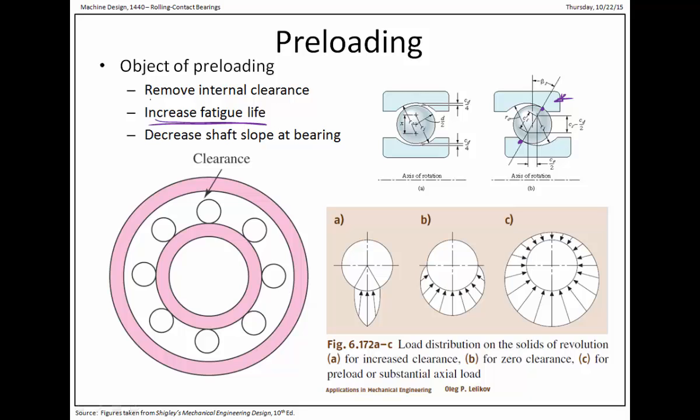One thing I think is a good way to associate this is that it removes any gaps or clearances that you might have. If you can imagine, if there was no load going on right here axially, this ball could move all over the place because of the little tiny gaps. By having a preload on there, it establishes where the points of contact are going to be. And like I said, it also generally increases the fatigue life.